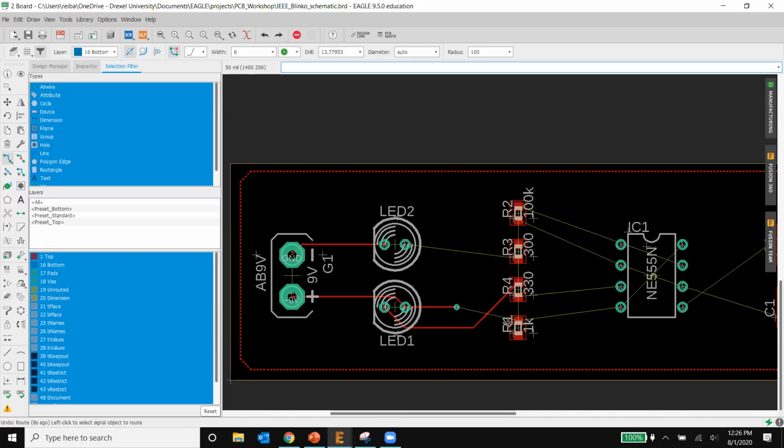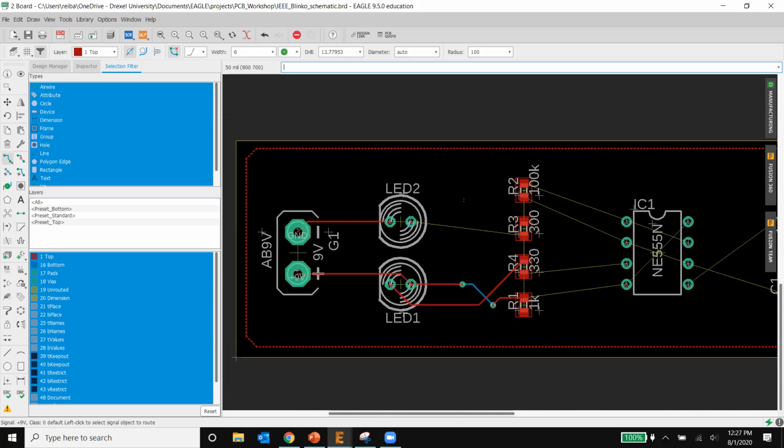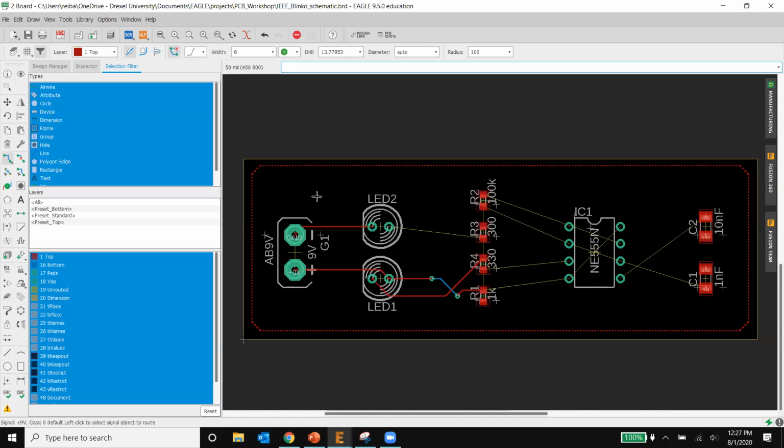Oh, I'm sorry, that was a mistake because it did not connect. So now you press the space again because you want to go to the first layer again because the resistor is in the first layer. So you left click and now you see that the wire is red again. So now you connect it. So as we see, we were first layer, go underneath this wire by going to the bottom layer, go to the first layer via copper connection, which is made with a drill, go back to the SMD that was on top. So that's a very important thing to know.